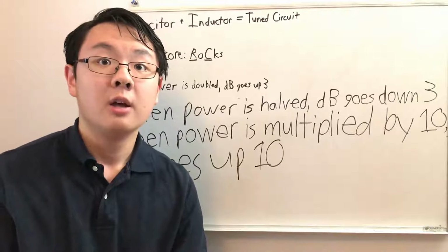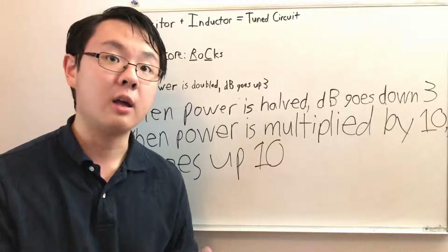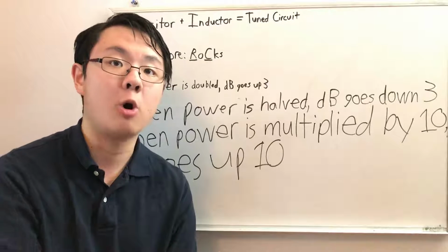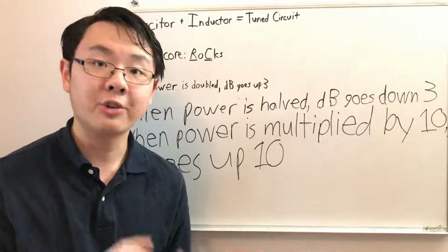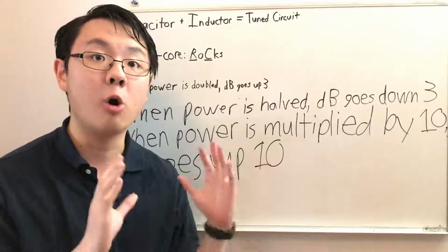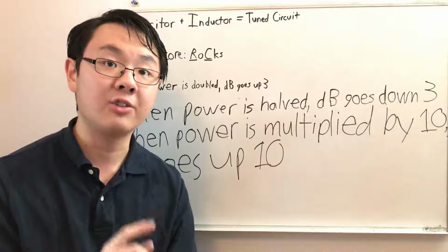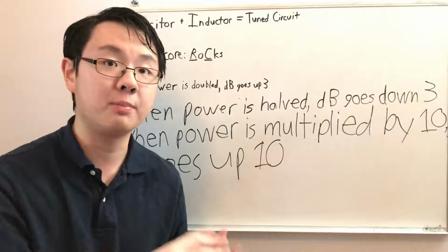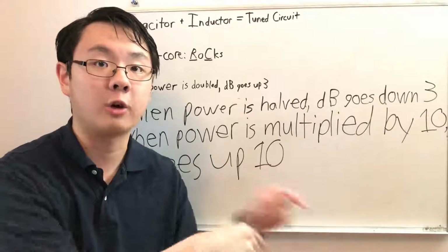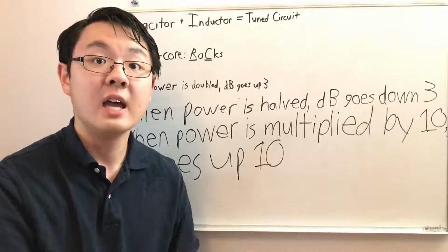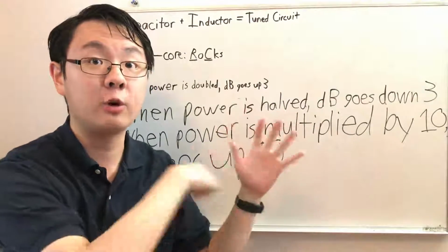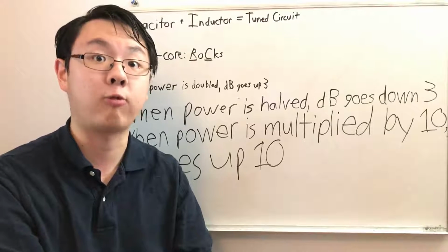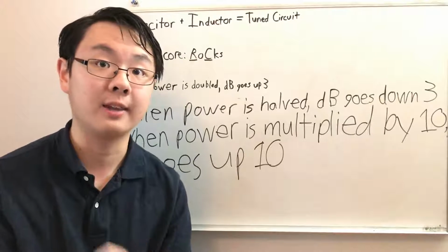That's very important. An ohm meter is not a multimeter. An ohm meter only measures one thing. Obviously it measures resistance. Remember, ohm is the unit for resistance. There's another tip I have for you that's going to be on the test about an ohm meter. Make sure that the circuit you're testing is off when you're measuring the resistance with your ohm meter, because you don't need the circuit to be on. The ohm meter will supply its own power through the circuit in order to measure the resistance. If you turn the circuit on and electricity is flowing through the circuit and you plug the ohm meter in, you're going to destroy your ohm meter. The ohm meter is going to get fried. That's obviously not a good thing.